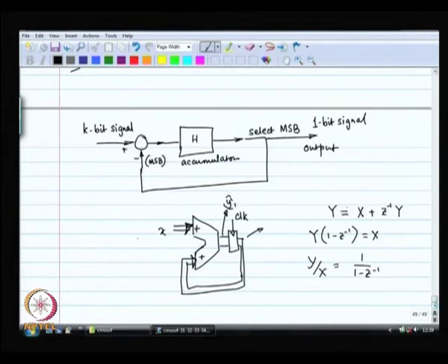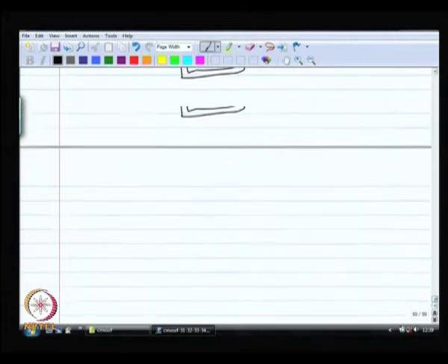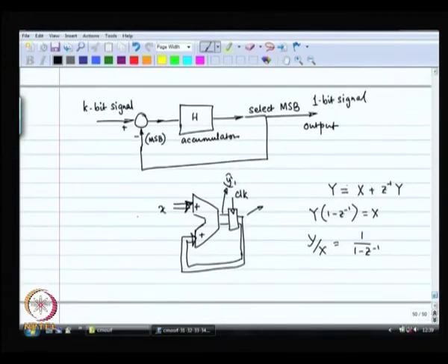Now, if I have such a scenario, then in the presence of the overall feedback, I am going to assume that there is some quantization noise because of selecting the MSB and discarding the rest. That is your quantization over there. Selected the MSB, thrown out the rest of the digits. You have quantized your number to certain two discrete possible levels.